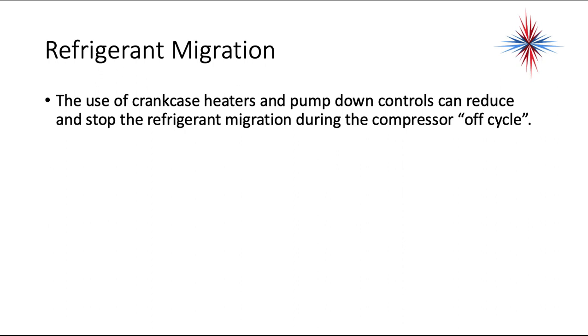This is especially important in the northeast or northern part of the country, where the cold winters sometimes cause liquid refrigerant to move out of the inside of the system and into the compressor and everything that's on the outside of the system. So we want to make sure liquid refrigerant does not migrate to the compressor. The best way to do this is by use of pump down or crankcase heaters. Crankcase heaters go around the bottom of, or into the bottom of, the compressor. All it's designed to do is keep the oil in that compressor warm. Warm oil prevents liquid refrigerant from settling in it.